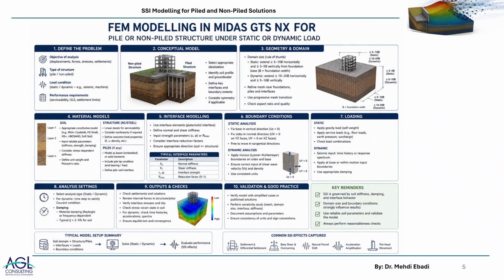And the important thing is that you are the designer. MIDAS is a tool. So you can't blame a program for something that you have no idea on the orders. So if you find that the numbers are far from what you get using hand calcs, they should be within the same order of magnitude.